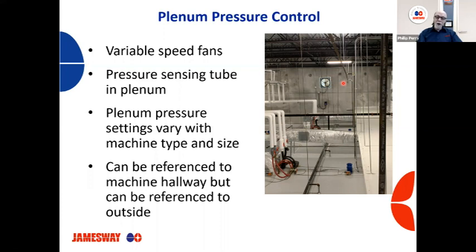So if one hallway has its own rooftop unit, its own air supply, independent from the other incubation hallway, but they're sharing the same plenum, then you would want to reference to the outside, so that if we're referencing the one hallway, but we have two hallways sharing the plenum, it might overcompensate or undercompensate for the other room. So this is when we would reference our plenum pressure sensor to the outside.